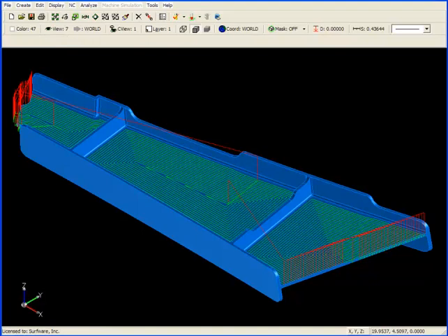Here's the result of our maximum Z level adjustment. We're machining the 3 pockets now, and only the 3 pockets, because they are the only flat surfaces below the maximum Z level we set. We're no longer machining the edges of the part or the tops of the ribs in the middle, because they're above the maximum Z level. Another thing we can notice is a number of rapid moves at each end of the open pocket. This is due to another parameter.